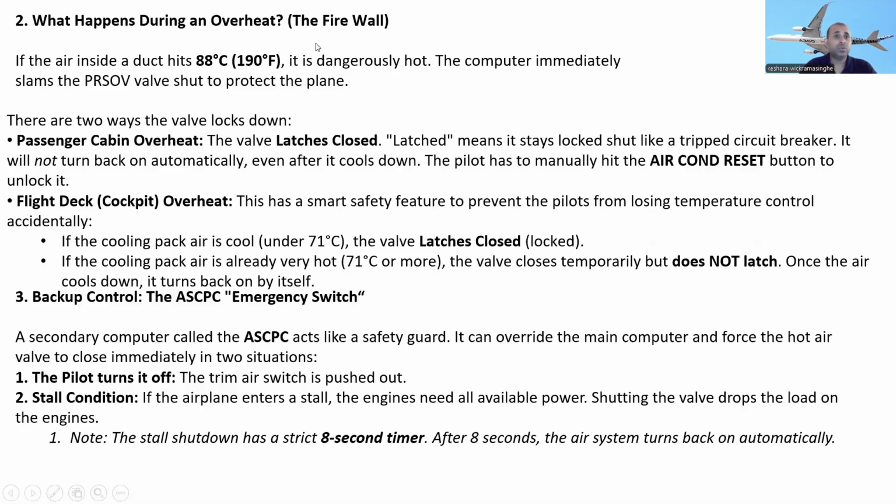Right, there are two ways the valve locks down. Passenger cabin overheat: the valve latches closed. Latch means it stays locked shut like a tripped circuit breaker. It will not turn back on automatically even after it has cooled down. The pilot has to manually hit the aircon reset button to unlock it.